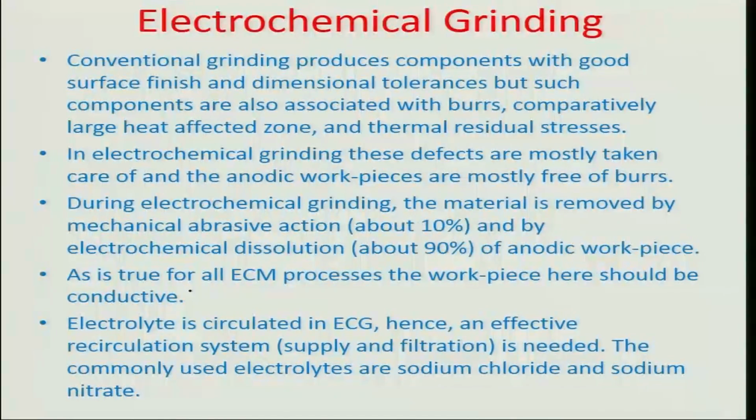So we can also talk about another application of the electrochemical machining, which is about electrochemical grinding. This is the process again where part of the job is done through mechanical action of the small abrasive grains which are there on the surface, and a major part of the material removal takes place because of electrochemical dissolution. So the electrochemical grinding is a little different from the normal grinding process, which is basically used to produce normally components with good surface finish.